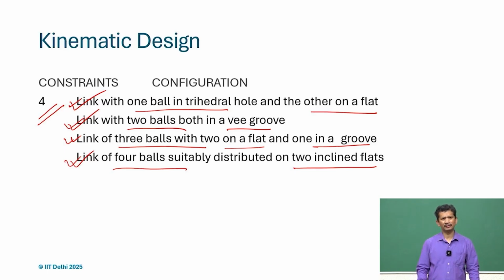If we compare these kinds of things with the conventional assembly processes, we realize that even if we change the dimensions or tolerances to 0.001 millimeter, or if we are talking about the perpendicularity of the surfaces, even if we just put a very small, negligible number to fool the software, even then it will not work, because the way it is defined is not exactly constrained.